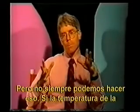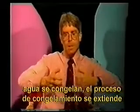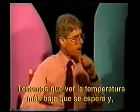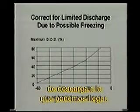If the battery temperature gets so low that the electrolyte and the water combination might freeze, the freezing process would expand and the battery would be damaged, perhaps forever. So we don't want to allow our batteries to freeze. We've got to look at the expected lowest temperature and, using a chart such as this, calculate the maximum depth of discharge that we can go to.